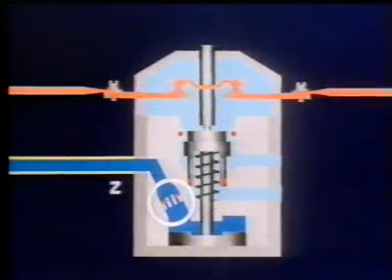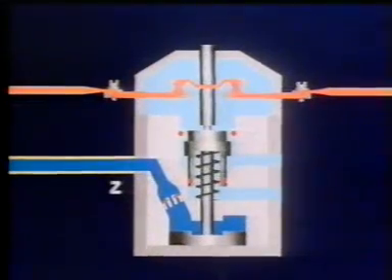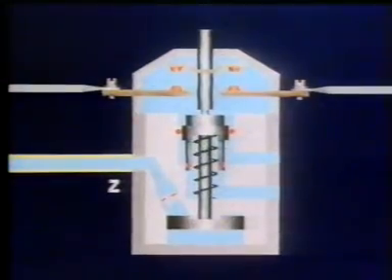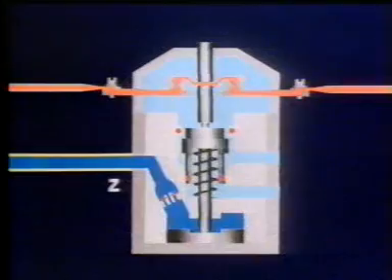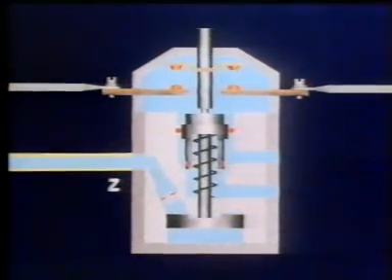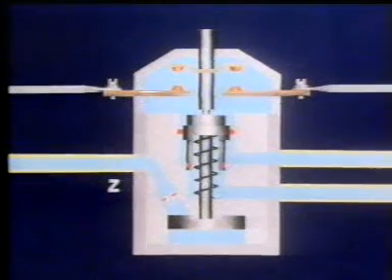The return orifice check valve has two functions. On the one hand, excessively rapid closing of the electrical contacts and thus excessive bounce are prevented when the compressed air is applied. On the other hand, the compressed air can escape quickly via the check diaphragm when venting. Premature contact wear as the result of sparking is prevented by the rapid opening. This design also allows the device to be used in a reversing contactor combination.